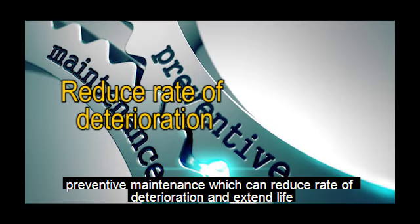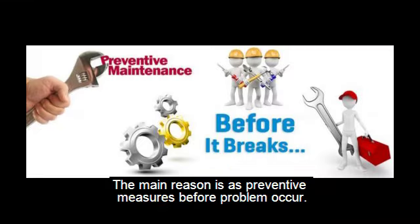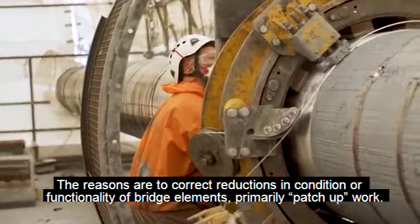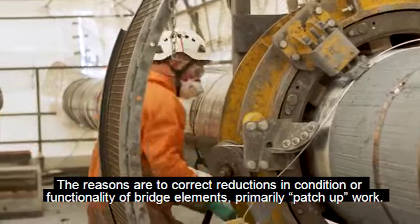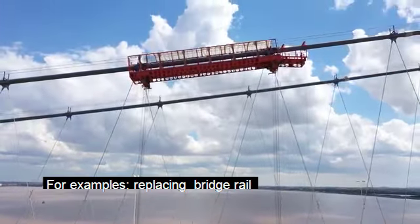There are 4 types of bridge maintenance. Firstly, is preventive maintenance, which can reduce rate of deterioration and extend life. It must be carried out on a regular basis. The main reason is as preventive measures before problems occur. Next is routine or minor maintenance. The reasons are to correct reductions in condition or functionality of bridge elements, primarily patch-up work. For example, replacing the bridge rail.